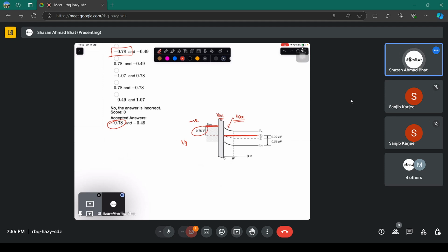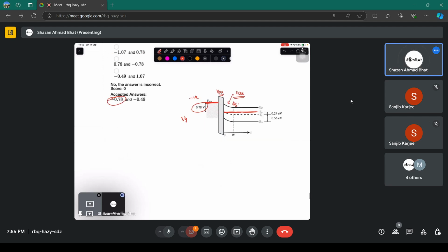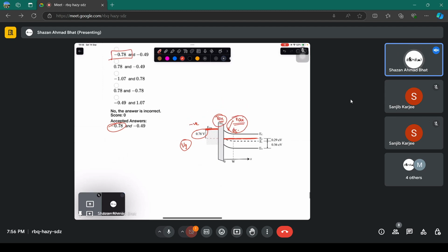At this particular surface, which is what you call the surface potential. It is just like Ohm's law. You apply some voltage, there is some drop. These are just like resistors. Now you have to compute the overall voltage. Whatever gate voltage you applied gets dropped at the oxide plus the semiconductor, and in the semiconductor it gets dropped at the surface, because there is a bending just near the surface.